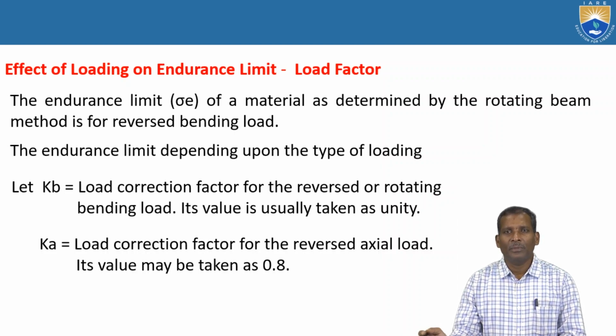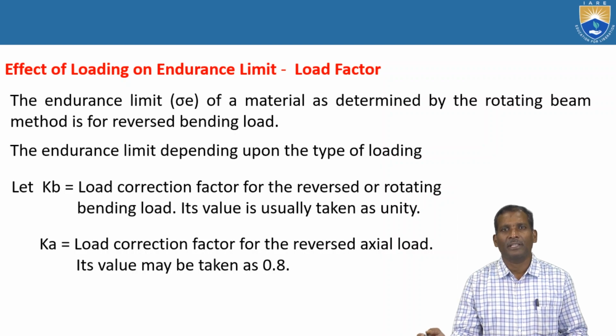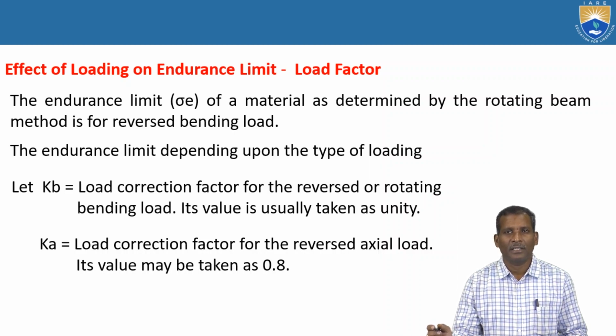The endurance limit of a material as determined by the rotating beam method, that is the fatigue testing method, is for reversal bending load. The same endurance limit we will take depending upon the type of loading, and we will multiply that endurance limit with these other load factors.